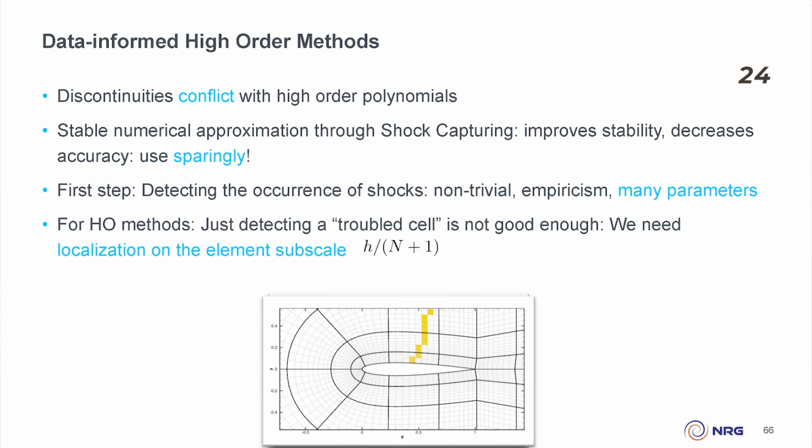Shock waves, as we've seen before when I talked about how we deal with shock waves, are difficult to capture because they're not smooth. So what one would need to do is some form of shock capturing, meaning some form of numerical adaptation of the scheme to the shock to capture the shock stably and accurately. But you want to use this shock capturing mechanism only when you need it, because it introduces a lot of numerical diffusion into your solution, which you only want at the shock zone.